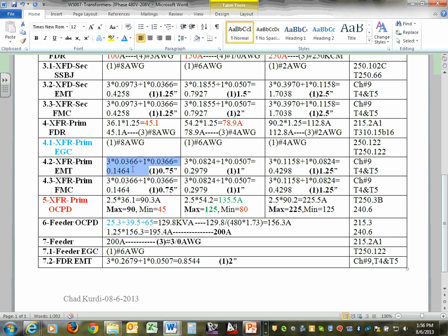Any comments how this calculation came to be, guys? Everybody knows you take the number of conductors multiplied by the cross-sectional area. All this information is coming from 250, Chapter 9, Tables 4 and 5. When we size your conduits, because ultimately we as the designers and engineers, we have to size the conduits and the wires. That's our job. Any comments, guys? Any questions?